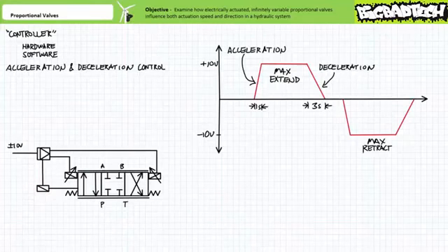Additionally, note that the position box of proportional valves sometimes have over and under bar lines to indicate that these are not mutually exclusive discrete positions, but rather infinitely variable. Additionally, proportional valve schematic symbols sometimes include flow control valve restrictions internal to the position boxes to make it explicitly clear that position influences flow rate. The onboard electronics may necessitate connection to a power supply, as well as a potentiometer used to adjust set points. These additional connections may or may not be explicitly illustrated on a schematic.